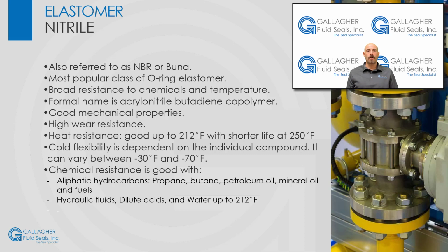Nitrile-based elastomers are not compatible with the following. Fuels of high aromatic content. For flex fuels, a special compound must be used. Aromatic hydrocarbons such as benzene, or chlorinated hydrocarbons. Polar solvents like ketone, acetone, acetic acid, and ethylene ester. Strong acids, brake fluid with glycol base, ozone, weather, and atmospheric aging.